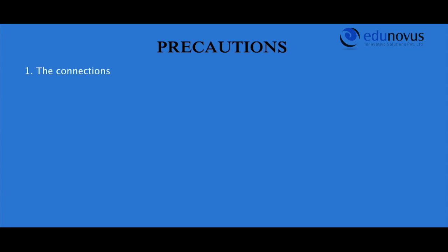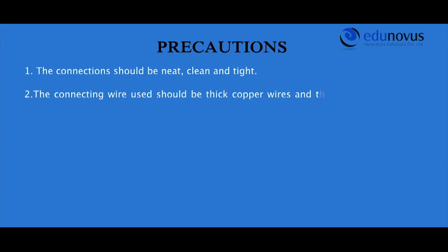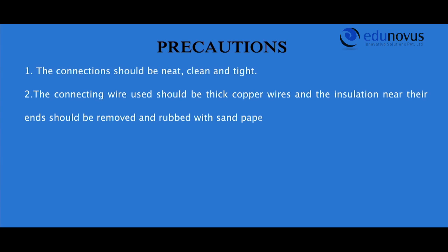The connections should be neat, clean and tight. The connecting wire used should be thick copper wires and the insulation near their ends should be removed and rubbed with sandpaper.